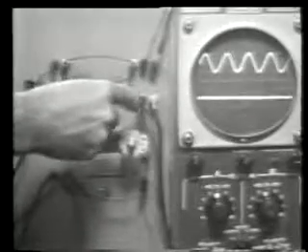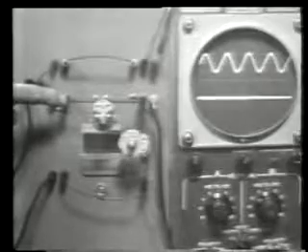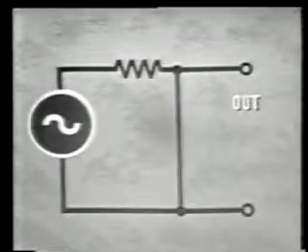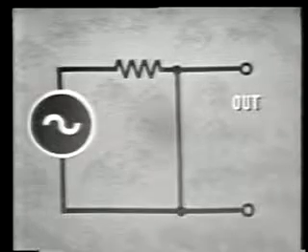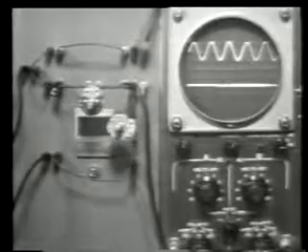We have all our voltage now being dropped across the series component. Our conclusion is then that to have minimum output voltage requires maximum series opposition and minimum shunt opposition. This is what we want our filter to accomplish.